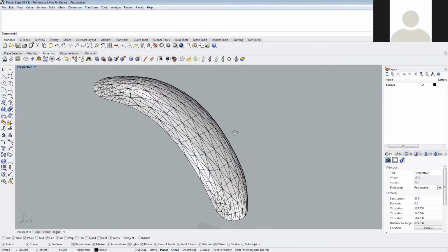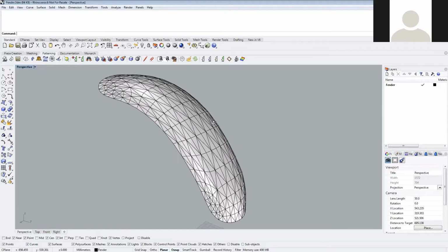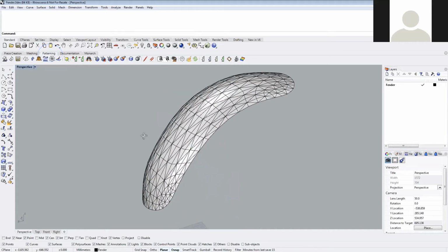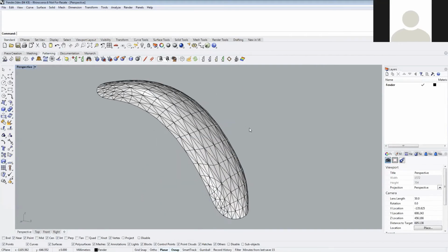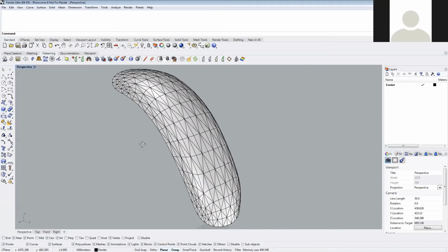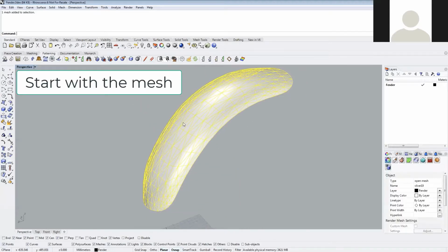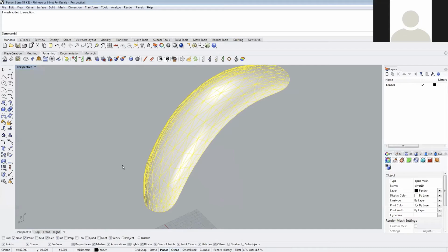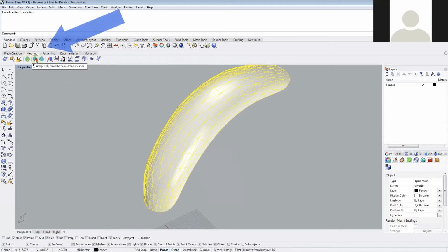We'll begin with the same model we used last time. So last time we talked primarily about the flattening capabilities of Composite Flat. So we were looking at the patterning tab. And just a quick recap, in order to flatten this object, we start with a mesh. We always recommend that we use one of Composite Flat's remeshers. So these are actually in the meshing tab. So we're going to switch back here and we're going to use the Adaptive Remesher.